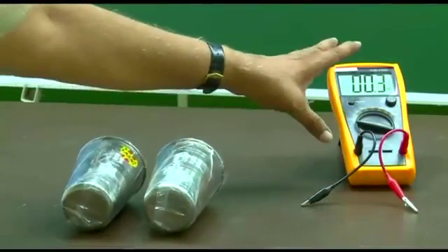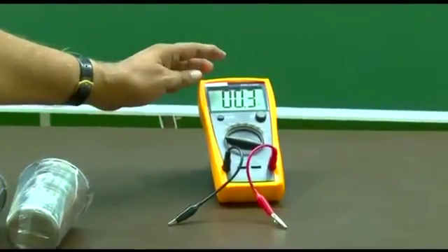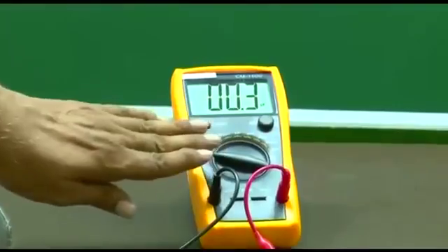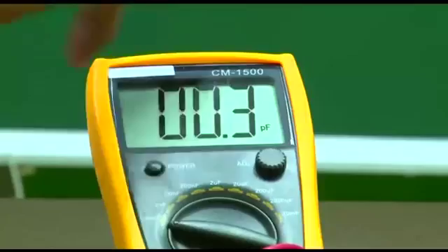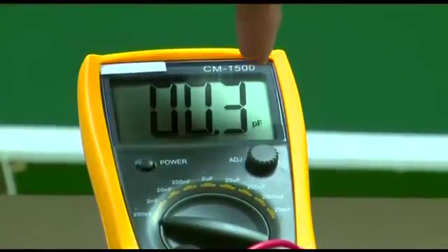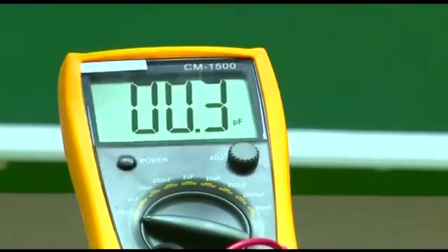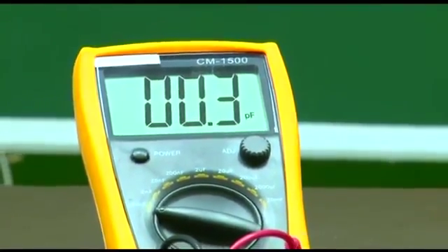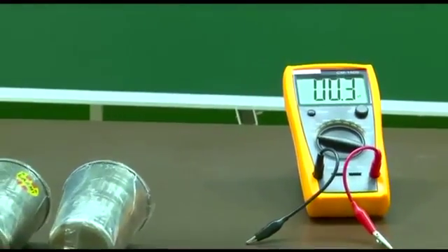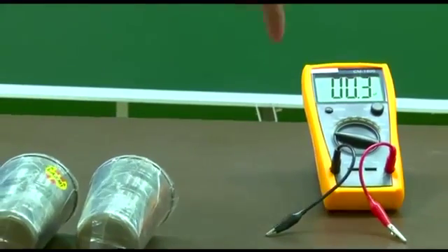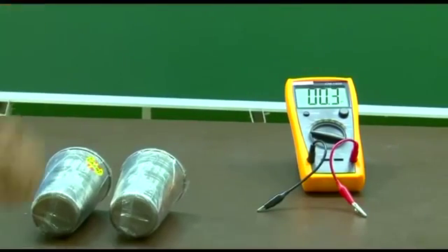First, let me show you the meter. This is the capacitance meter, and we have set all those values, range, etc. And the display here is in picofarads. On the right side, the small letters say PF. So, it is picofarad. Pico means 1/1000 of a nano, 10 to the power minus 12. So, those many farads, right. So, it will measure in this. This 0.3 is your zero error, you can assume that.